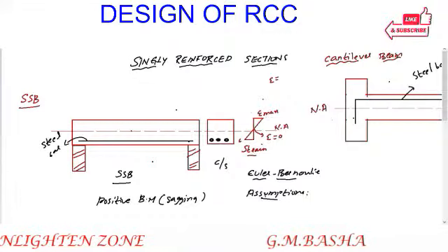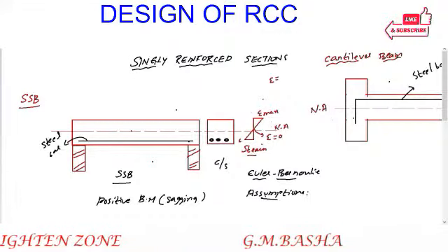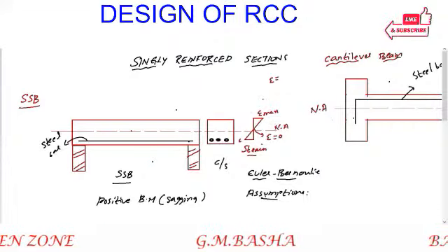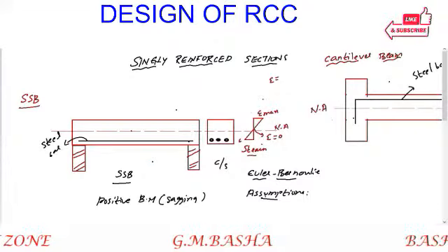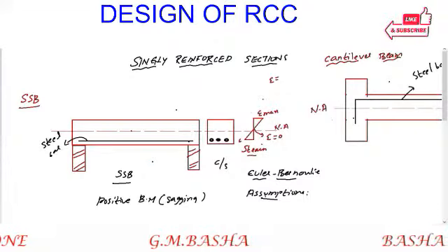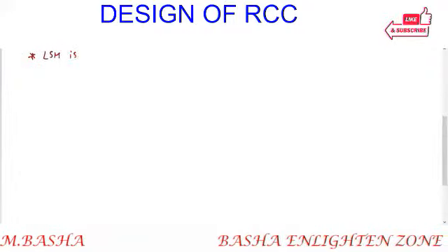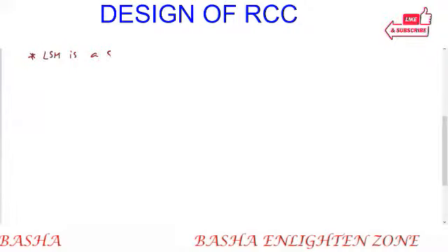So this Bernoulli assumption is valid for two different materials, means composite members are also valid up to the failure. Okay, please remember this Bernoulli assumption also. Then we'll talk about similar concepts related to the singly reinforced section and the continuation of the stress block parameters. Here one more point I want to add: this limit state method is a strain oriented approach.